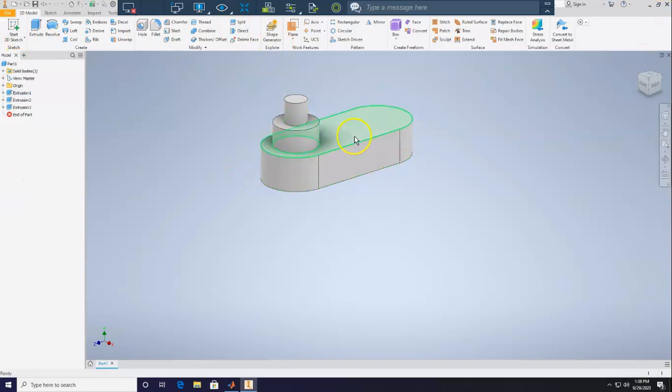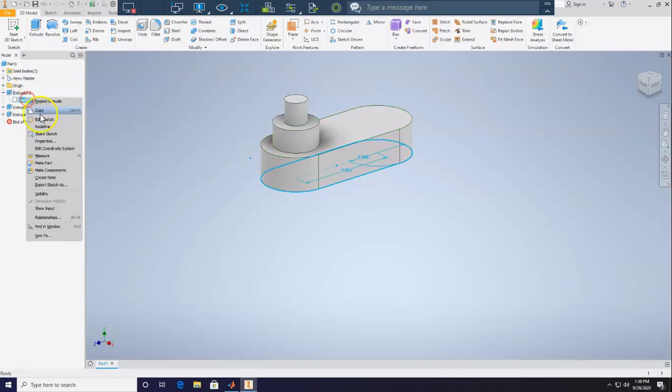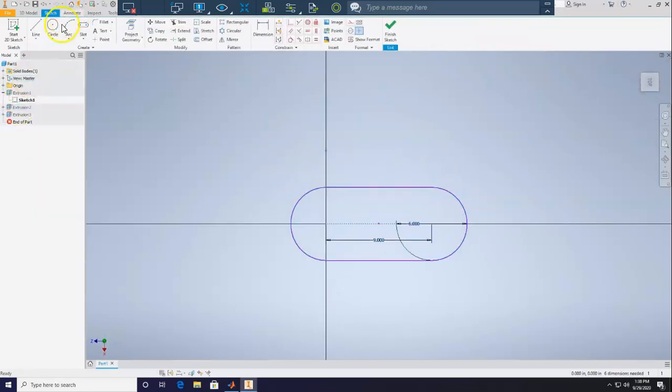So now we have to make the hole. There are two easy ways to make the hole. Actually, technically, I could have done the hole from the beginning. If I go back to sketch 1, I could have, on one of the sides, I think it was this side, made the hole. So this is just a hypothetical of what I could have done. I could have made a little circle right here, and you could click on this center, and if it doesn't appear, you can always hover over it, and then it usually appears.